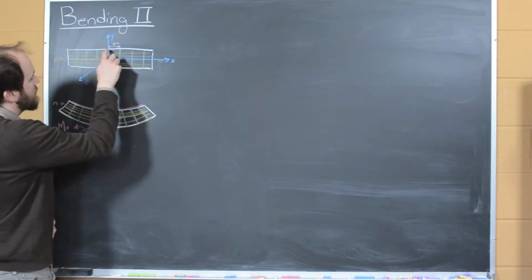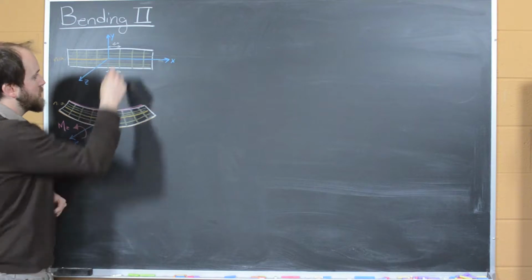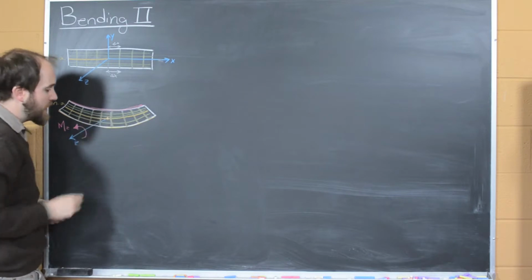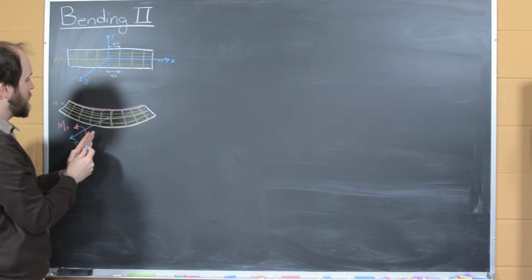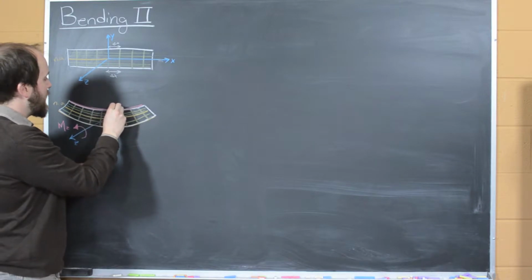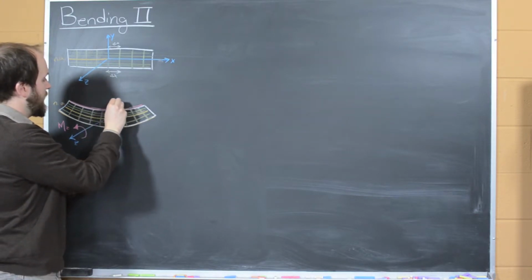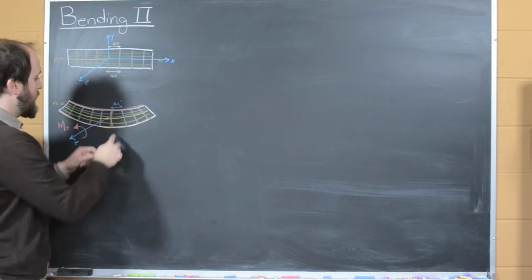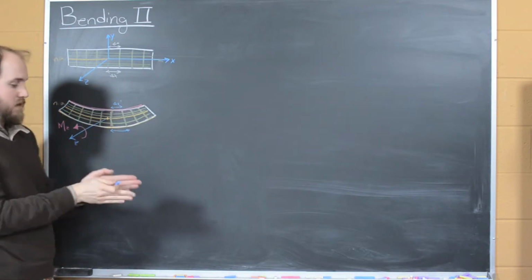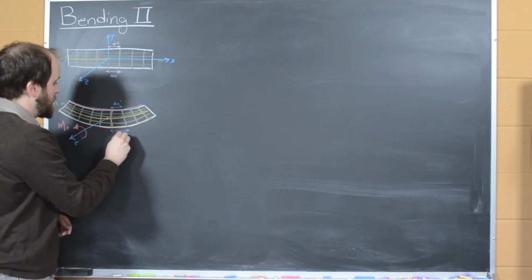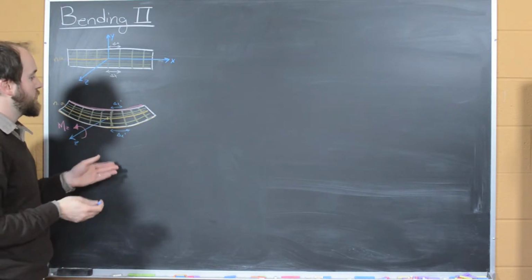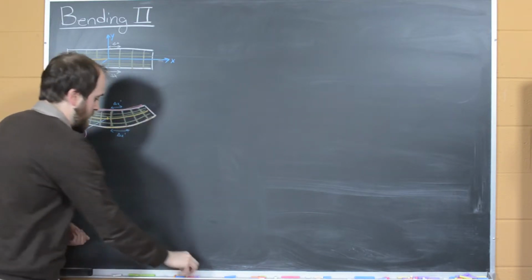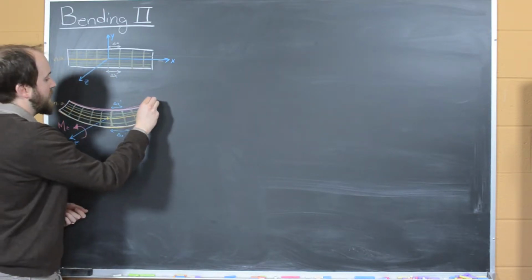And this has an important consequence, which you can possibly see right from the outset, which is that in this undeformed case, the length between here and here, some arbitrary point, we can denote as delta x. And as you look at the deformed case, what you should start to see is that at the top of the beam, this delta x, so maybe we'll call it delta x prime, is now smaller than this initial case, and at the bottom, from this splayed angle, this delta x prime is larger. So what you should be able to see right from the get-go is that the top of the beam, what I denoted with this red line here, is actually in compression.